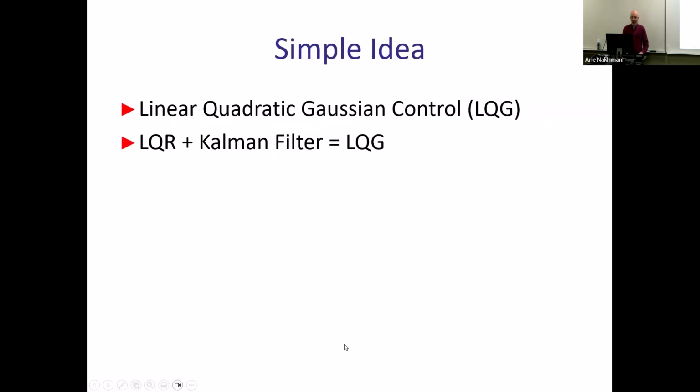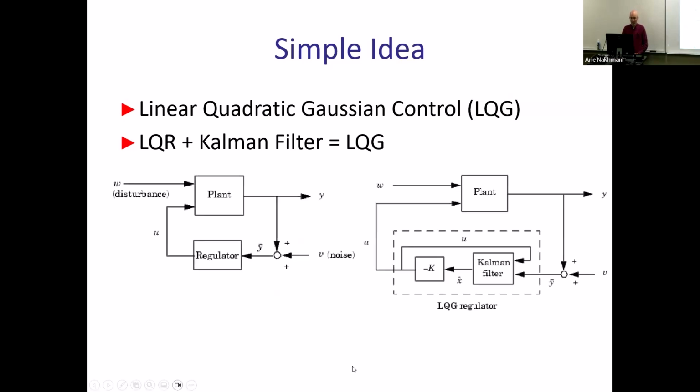All right, so linear quadratic Gaussian control is just, as I said, adding these two together. And in block diagram, it will look like that. So in a sense, you'll have now two inputs to your actual plant. One input will be some disturbance or noise. If you remember, we multiplied GW, which was added to the system. And you can think about that W as additional input of noise or disturbance, okay? So this will be the disturbance input. And this U will be just output of your regulator, which is LQR in that case.